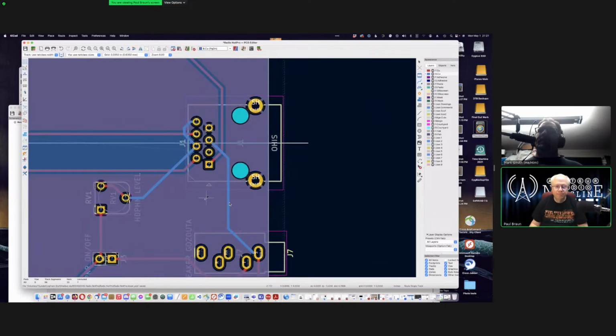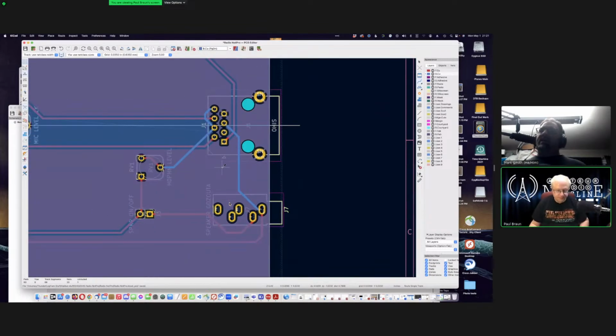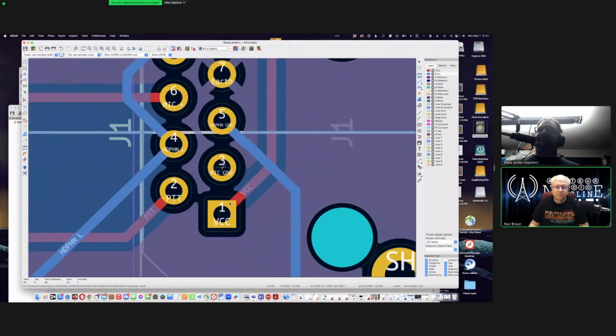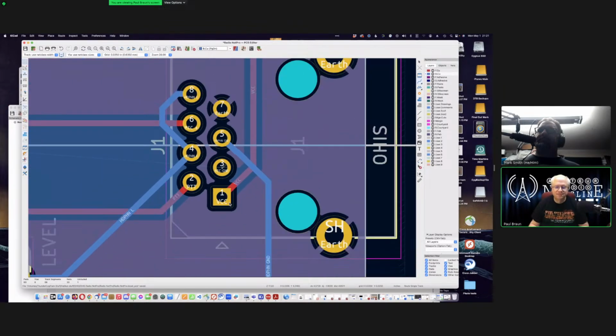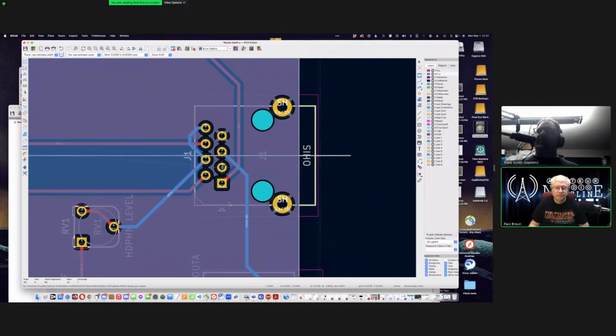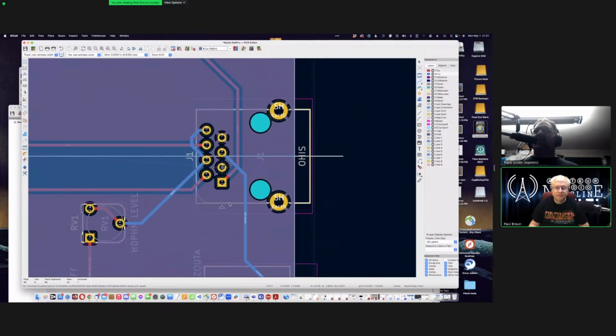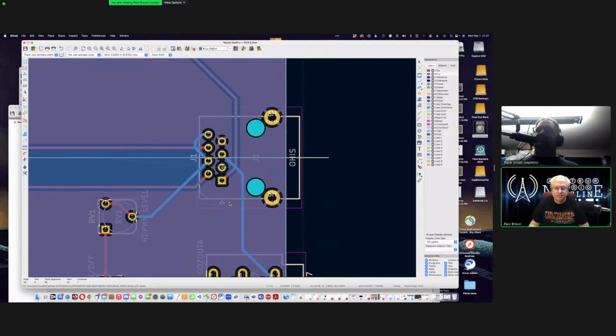There you go. Right. Now, unfortunately, we have cornered in the mic ground on pin 3. Yes, we have. So I think what I'm going to recommend is for the headphone left trace, the blue trace on the left-hand side, delete those traces that are there. Like this one? Yep. All of those traces. Delete them all.